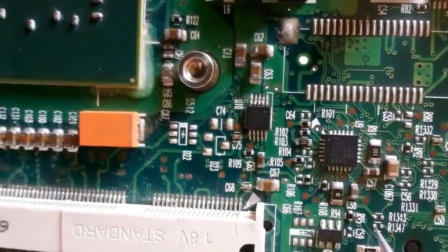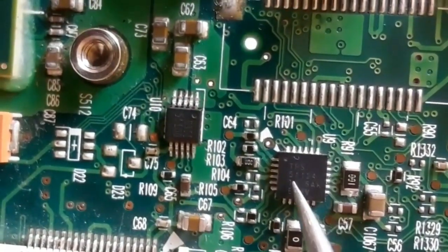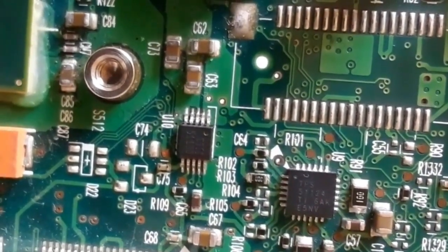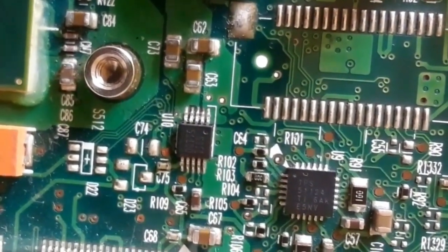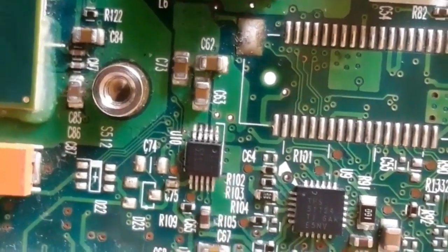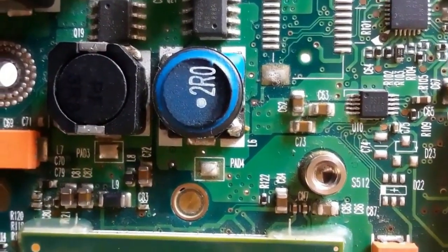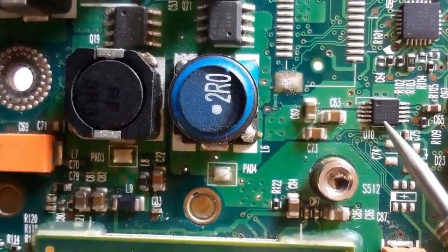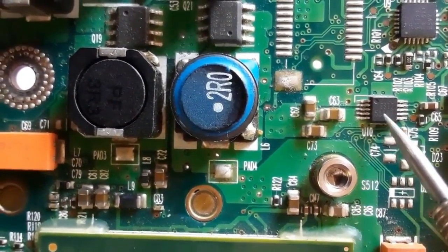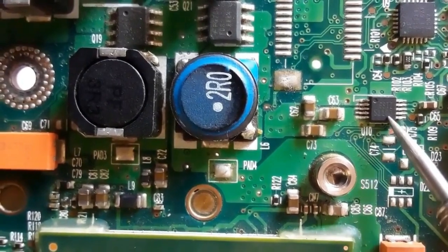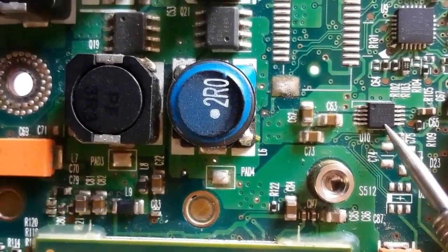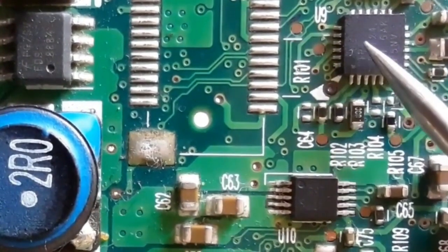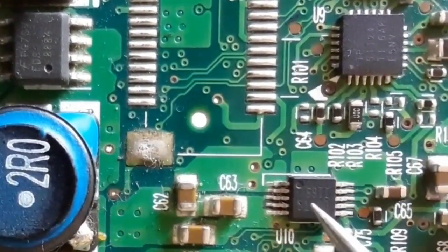This is, as you can see here, the 51124, as you can see on the right, and over here, as you can see, this is 51100. This is a power management IC that generates 0.9 volt for the VTT, the power, the RAM, the random access memory. So these two ICs, you will always find them near to each other.